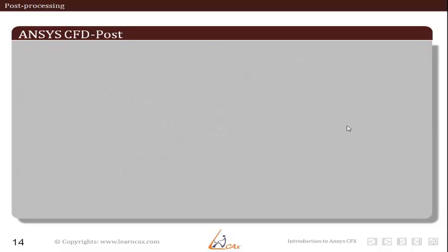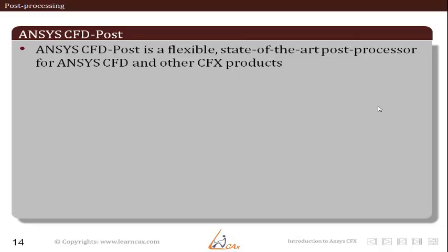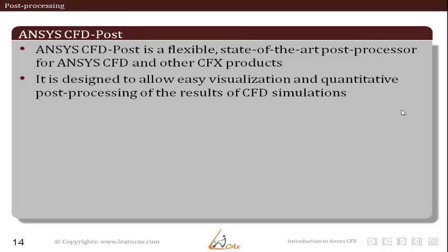Now let us see what are the different options of visualizing results when you solve a CFD problem in CFX. For this, ANSYS provides another module or software graphic user interface called CFD Post. What is ANSYS CFD Post? It is a software for extracting results. It is highly flexible to use and can be used as a single post-processing environment for analyzing results from any of the ANSYS CFD solvers and especially CFX. It is designed for easy visualization and provides many options for result analysis.